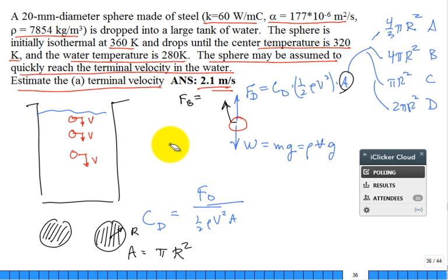And so what does it say? Archimedes' principle says that the buoyancy force, F buoyancy, is the weight of the fluid displaced by my object. Well, how do I calculate the weight of the fluid displaced by my object? Get the density of the fluid, the volume of the object, and g. Look good? Archimedes' principle: the weight of the fluid displaced by my object is the buoyancy force.